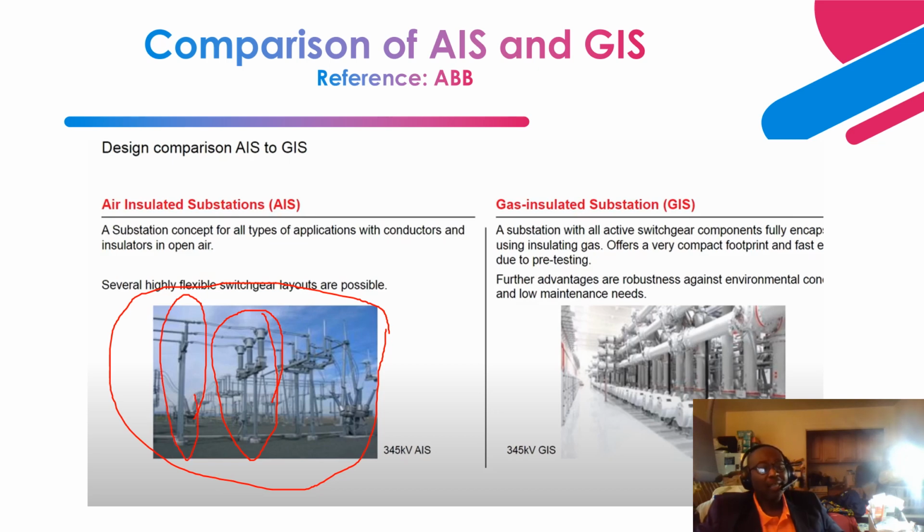As you can see over here, for an air insulated substation, look at the larger footprint that you have. Very big, and talking about the cost and also reliability, it is prone to birds, animal strikes, etc. And pollutants. You have all the contaminants in the air resting on all these components, and especially the insulators. You have porcelain and polymers, and they are all exposed to the elements.